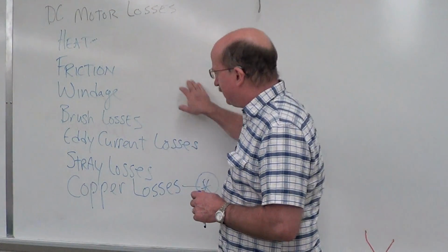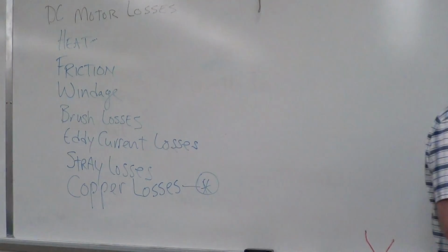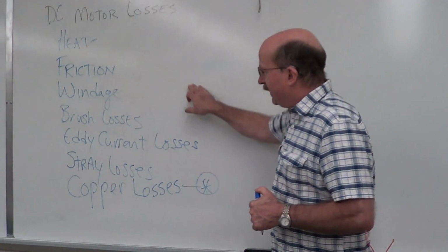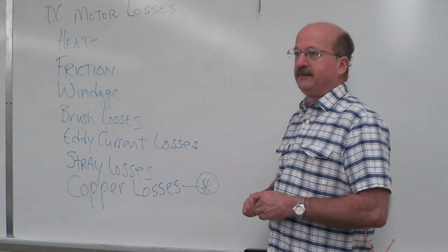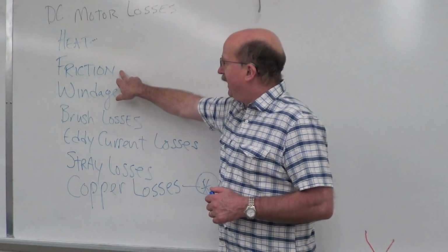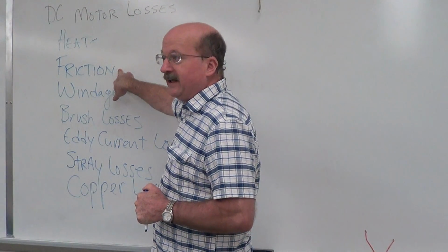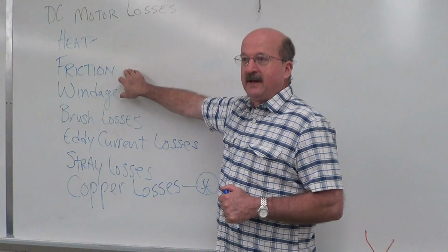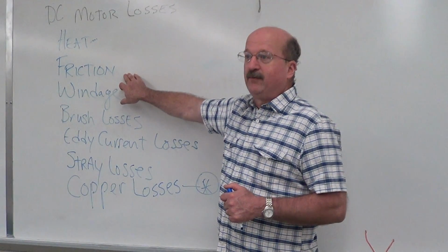And then you have the rest of them, which all lump in. They're not going to change. The motor is running at a constant speed. All of these are fairly constant, but they are things that go into the makeup of the motor. Your friction, you can't really change the bearings, but as the bearings get dirty, if you're not keeping the brush carbon out of the bearings, your bearings are going to start to wear and your friction's going to go up.